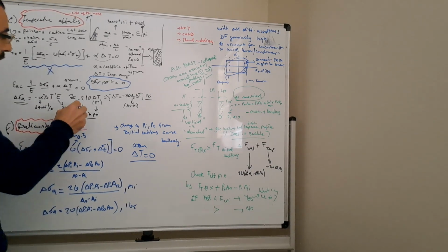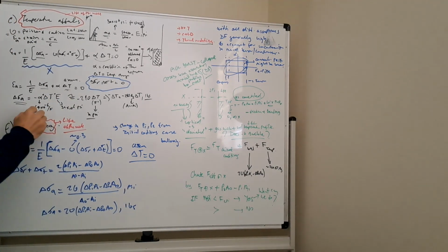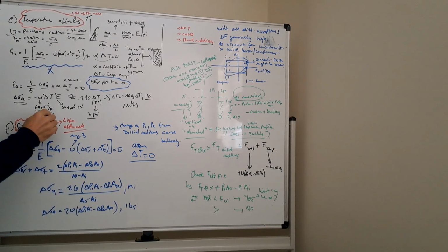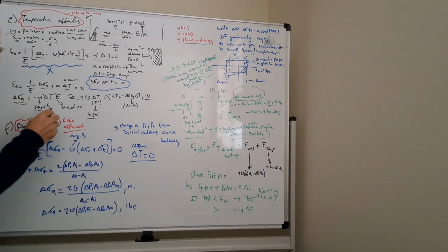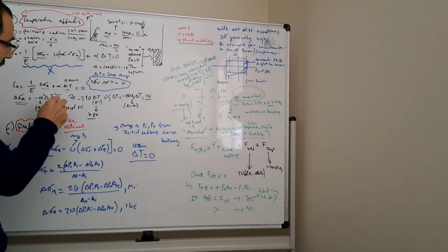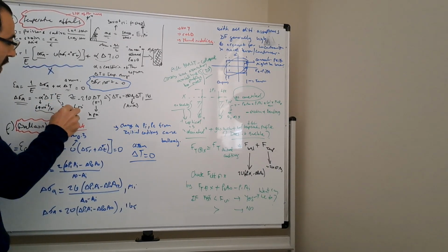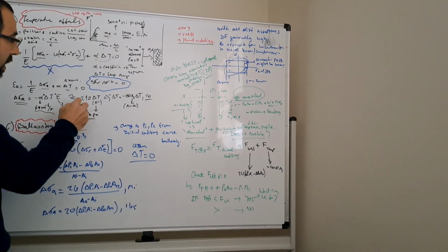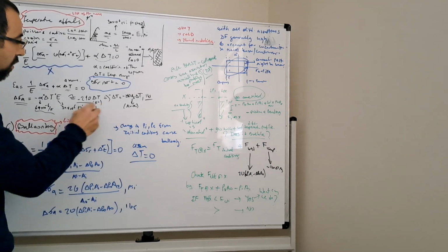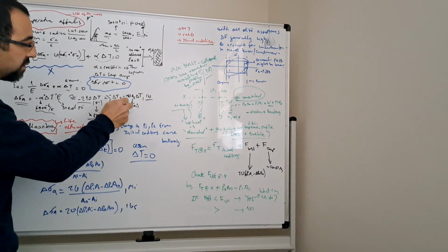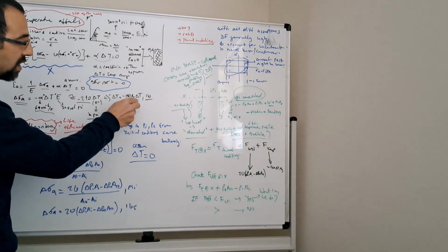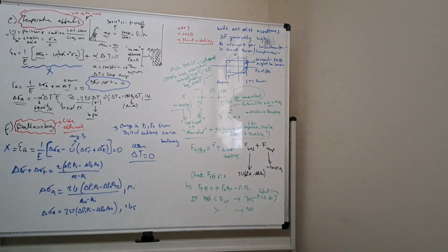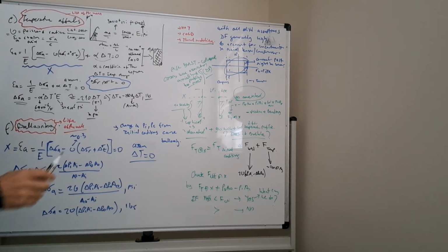You round it up: the coefficient is almost 7 times 10 to the minus 6 per Fahrenheit, and Young's modulus is 30 times 10 to the 6 psi, as I mentioned here, for steel. And then you end up with this simple formula of minus 210 times cross-sectional area times the delta T in pounds.